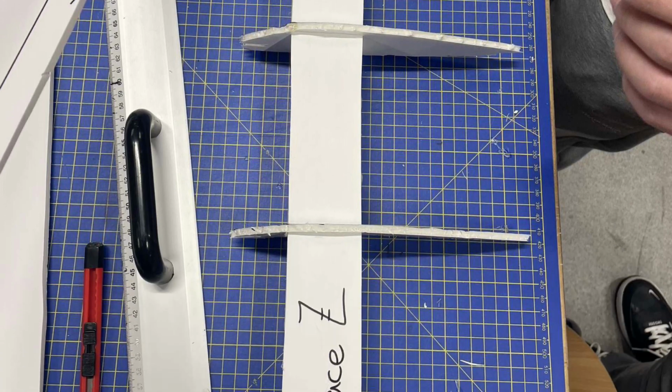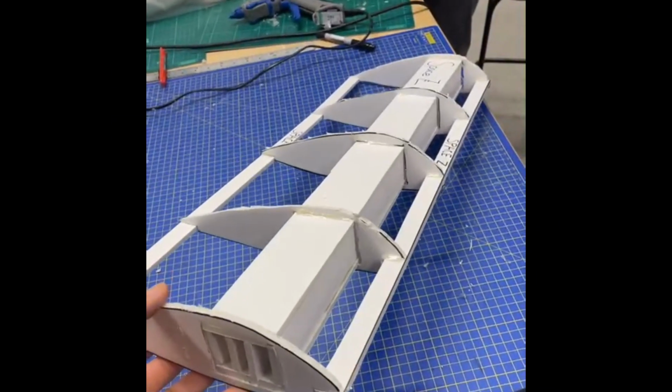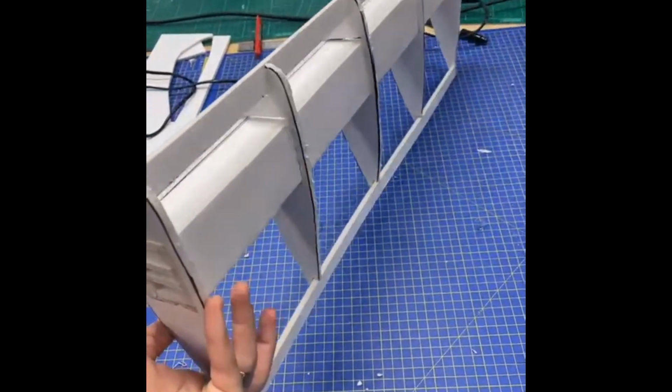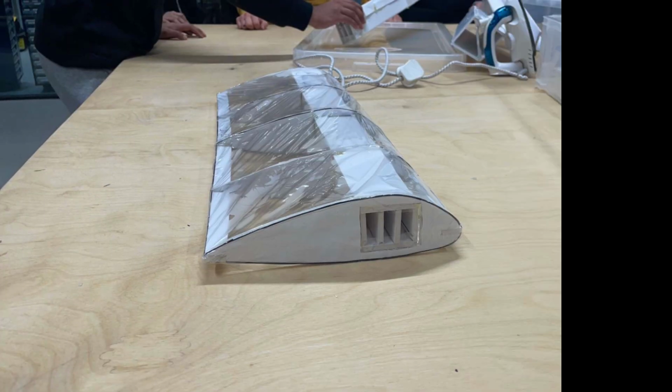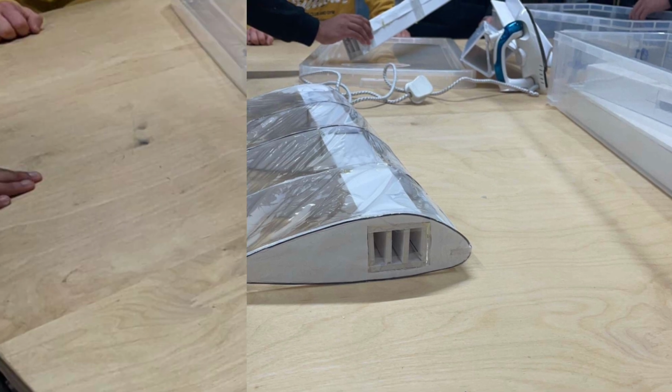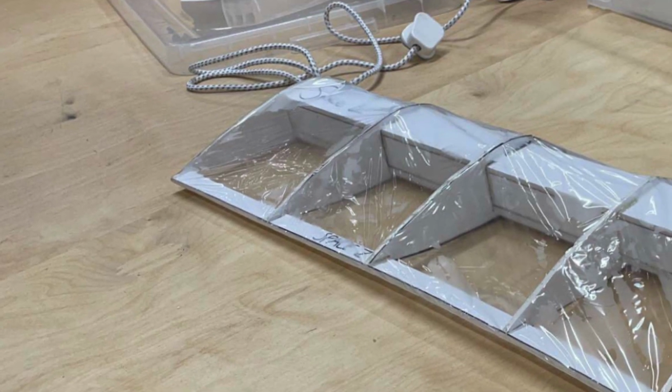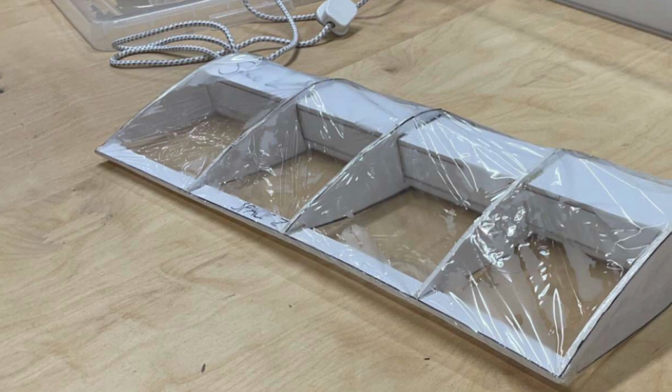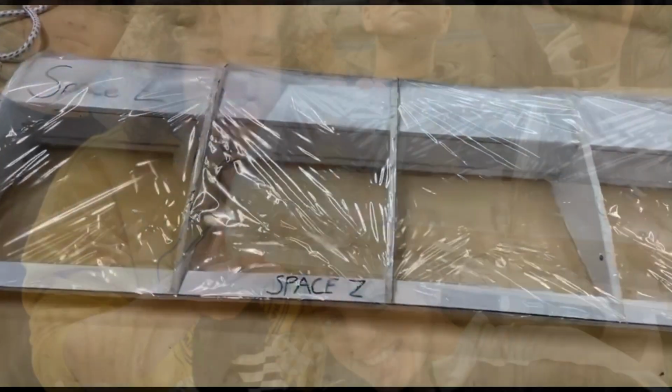One improvement we could have made is our aerofoil shape. In Excel it fit requirements, however in the lab, the gap for the spar and the edge of the aerofoil would have resulted in the structure being flimsy and unstable, so we had to create an allowance which resulted in it surpassing requirements. Also, our I-beam spar could have been improved by cutting holes in the spar to reduce weight.